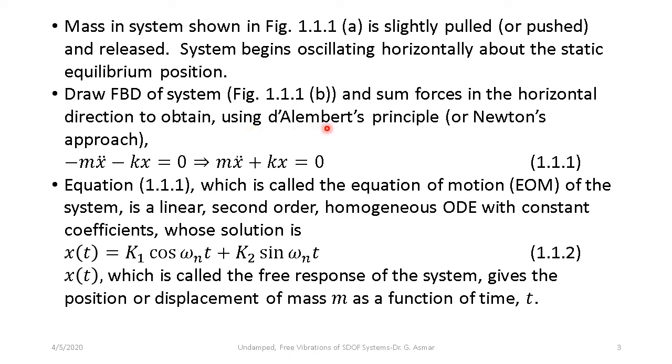Of course, if you choose to use Newton's approach, Newton's second law of motion, sum of forces equal to ma, then you would arrive at the same result. The two methods are equivalent. I prefer to use D'Alembert's principle because I think it's simpler, particularly when you're looking at more complex problems than what we have here at hand. So you sum the forces and you obtain an equation of the form m x double dot plus kx equals 0.